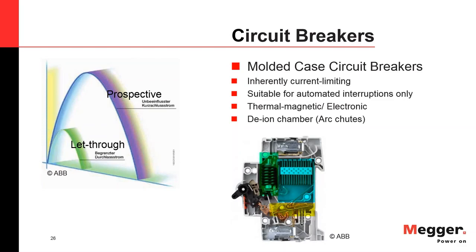Now there is an interesting effect that at those foot points additional voltage drop is created, and that is mainly a function of the material. It's not a function of the current or anything else. So you add a lot of foot points and the voltage drops across these foot points. You also elongate the arc, and you at the same time cool the arc. And with these three effects, splitting or separation and creating more foot points, elongating the arc and cooling the arc, the arc will vanish within a few milliseconds, and the circuit is interrupted.